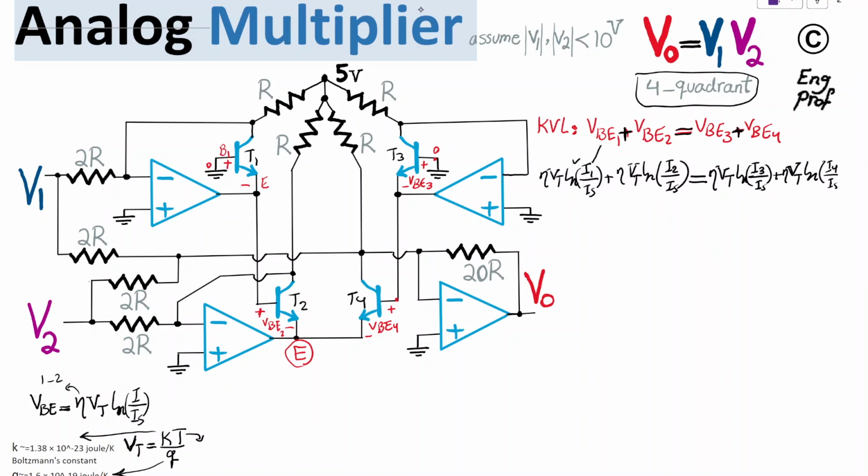Okay, so what is going on here now? All right, so we can get rid of the ηVt, so this one cancels out on all sides. And then what I get after this line is effectively ln and then ln of 2ln summed up together on one side. I can just multiply the argument. So I1, I2 squared equals, on the other side, natural logarithm, I3 times I4 squared.